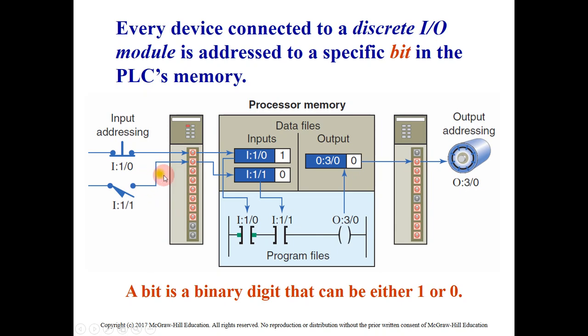interface is. Okay, so for that, the numbering usually starts from 0. So you can see here, this is terminal number 0, that one is terminal number 1, and so on until 15 here. If it's 32, it will be until 32, 64, and so on. Okay, so you can see here, this is the address on the hardware device. It's identical with the address here inside the memory. Okay, so we have the processor memory here.